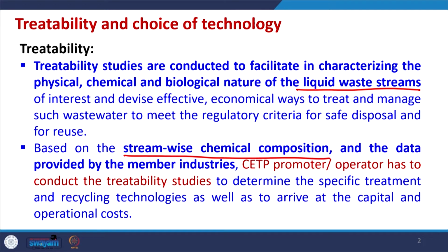Depending upon the data provided by the member industries, the CETP promoter or operator has to conduct treatability studies beforehand at laboratory scale, plant scale or pilot scale to determine the specific treatment and recycling technologies to be adopted in the CETP for minimizing both the capital and operational costs.